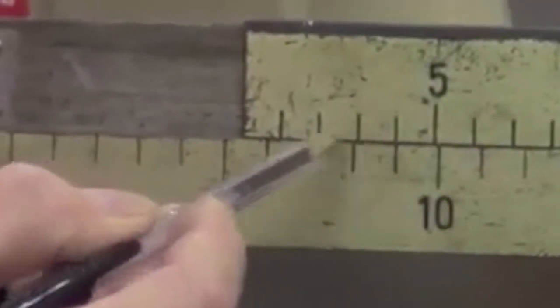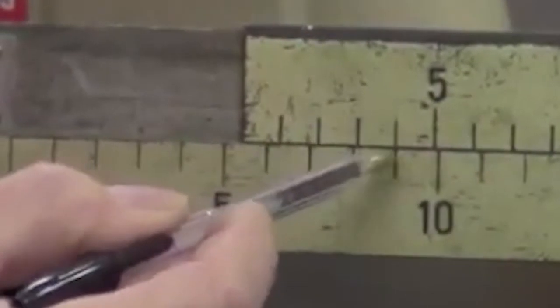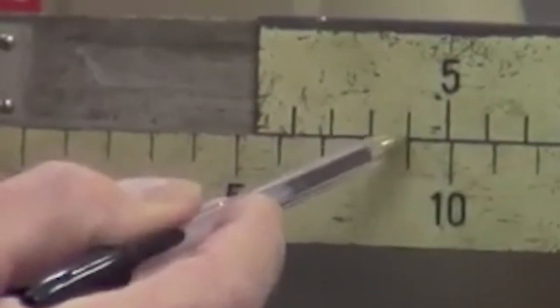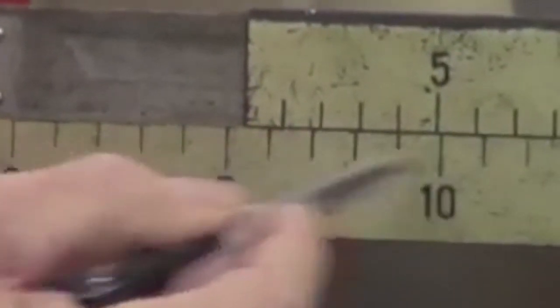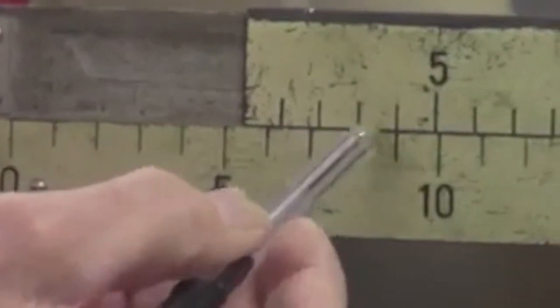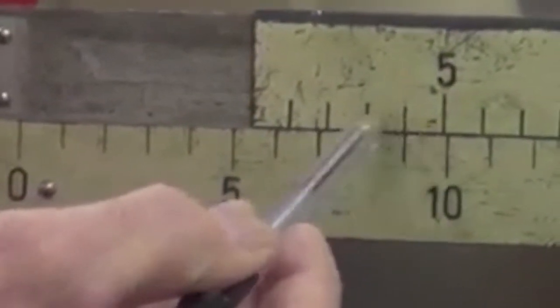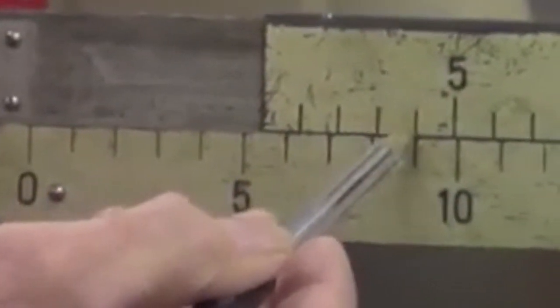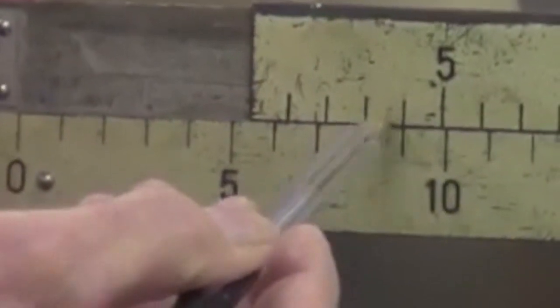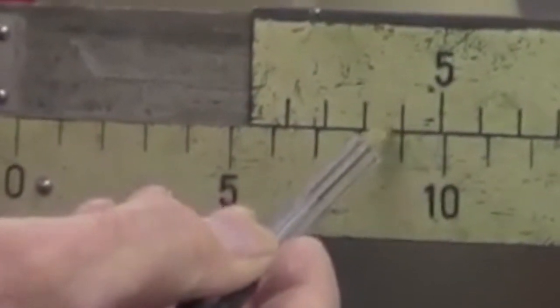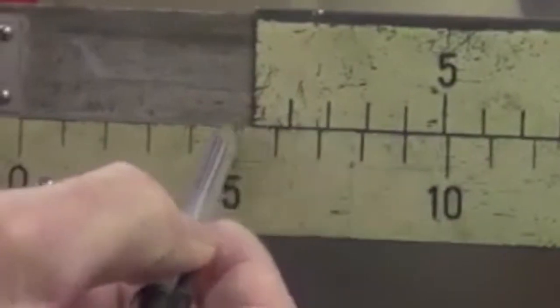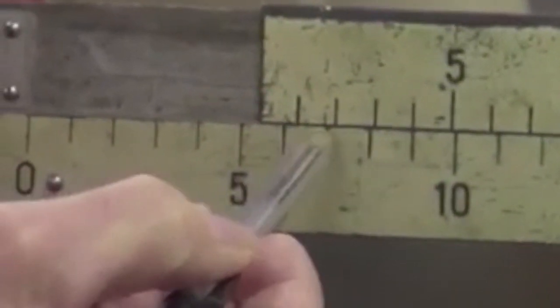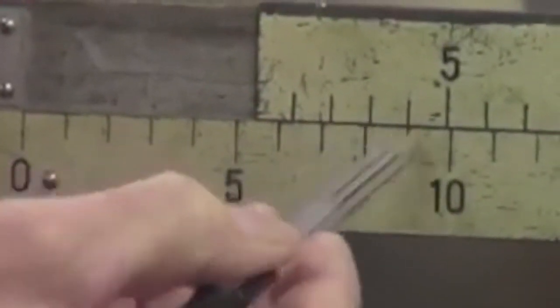It's pretty clear that these two lines line up best with each other out of all the lines on the scale. That's because each one of these lines is closer. So the fourth line is 4/10 closer, meaning that this is 3/10 closer, this is 2/10 closer, this is 1/10 closer, and that's right on the money.